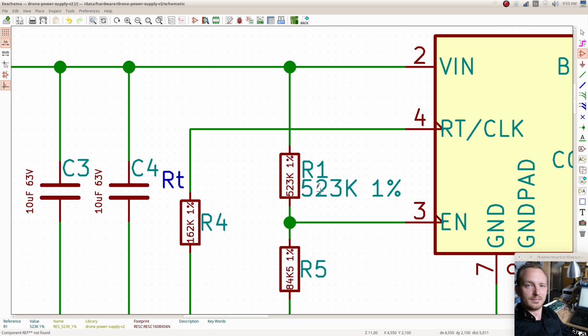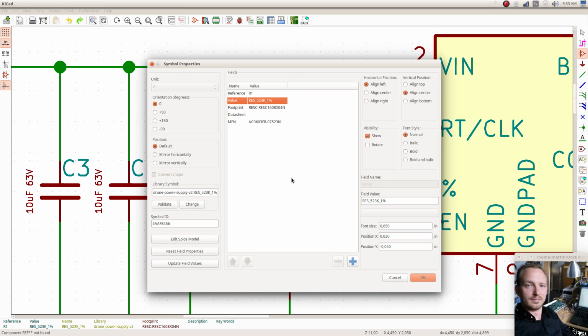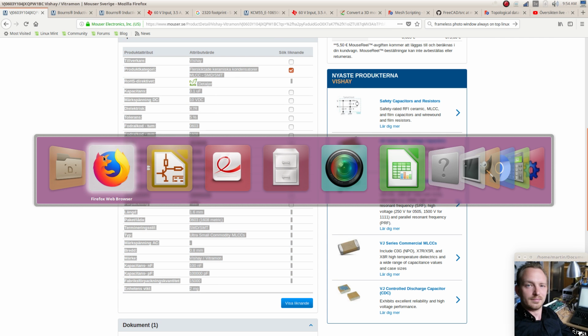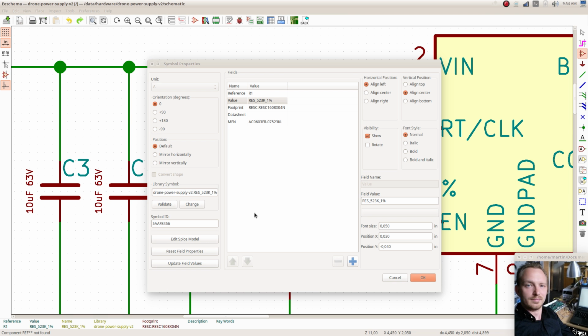Instead, you can just specialize it in the library and then duplicate the same component and know that the manufacturer field is always going to be there and always going to be correct. And any other fields, like if there was a functionality to import components directly from Mouser, then typically I would have all of this already imported into the fields here.